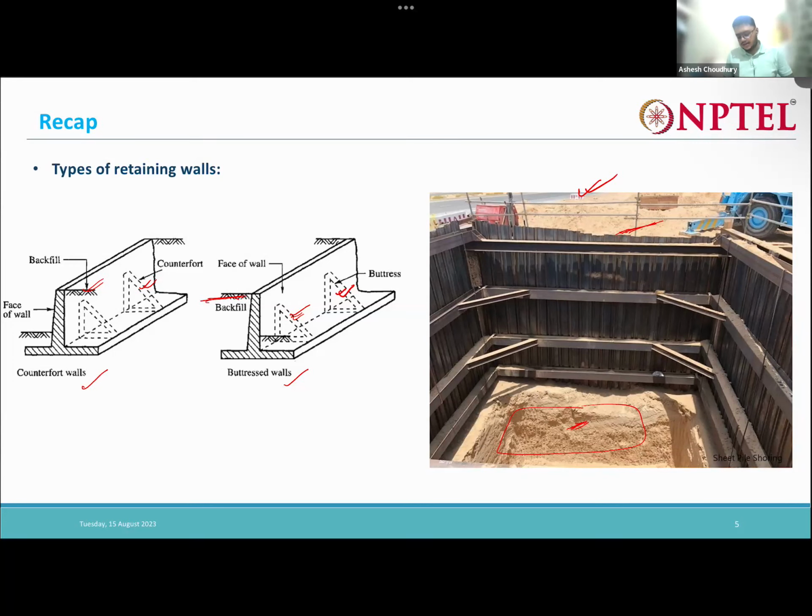So that is actually sheet pile. Here you can see the sheet piles. These are the sheet piles, and what you do is drill them into the soil. There are some tools available which you use to drive the sheet pile into the soil, and there is some interlocking between the sheets. So these two sheets will interlock here. You need to drive it.